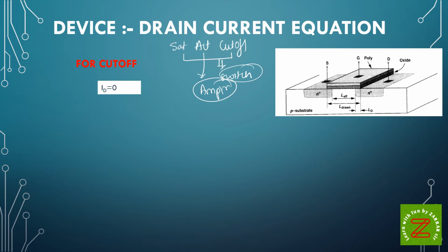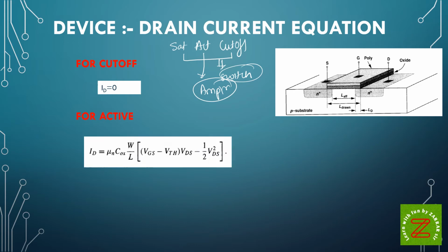Drain current in the cutoff region, ID, is equal to 0, since there is no current passing from drain to source. Now for the active region, the equation involves the four parameters we discussed in our previous slide: channel length, channel width, voltages, and oxide capacitance. So you can see this equation.